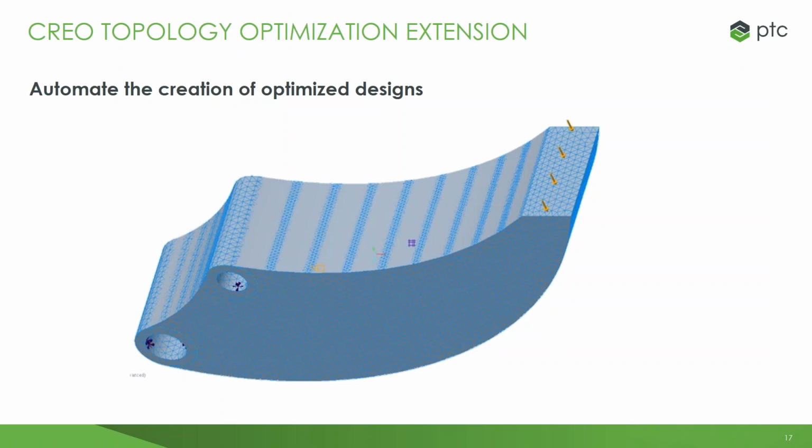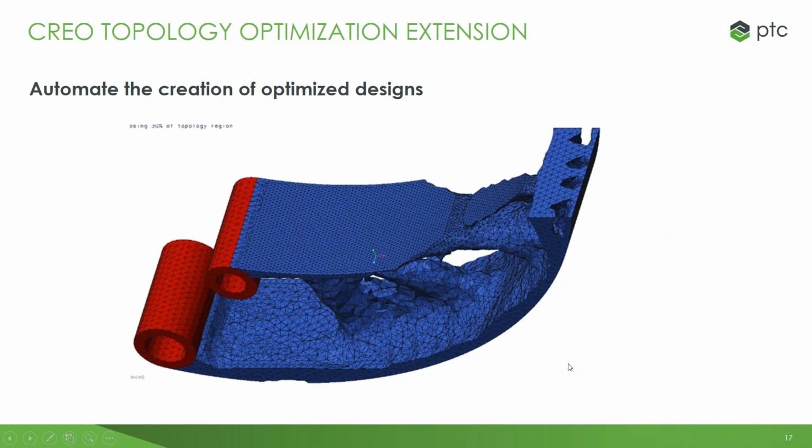So for this tooth here, we've got a number of forces and loads creating a number of stresses, strains, and torques on it, and the part works fine, but maybe we want to make it a little bit better. Maybe we want the part cost to be cheaper, maybe there's a better way to manufacture it, or maybe we could just use less material altogether. One way to go about this is we could use hundreds of iterations and simulate and test different ideas that we have. Or we could use topology optimization and just give it some constraints and design parameters, and the program's going to do the rest for us.